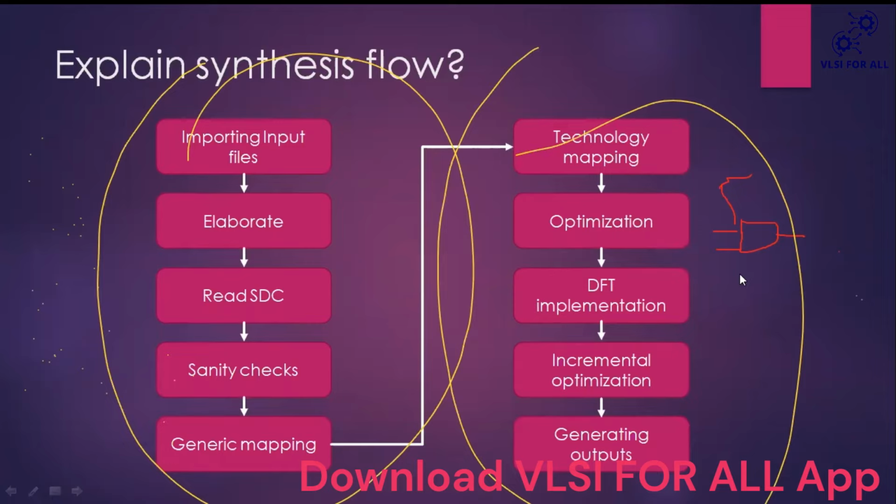During optimization it will also do this separately. During generic mapping, the tool does optimization. In technology mapping also, the tool does optimization. But separately, after mapping all the RTL code, I mean after converting the RTL code to a gate-level netlist, the tool does optimization separately. As I said, timing, area, and power. These three the tool tries to meet.